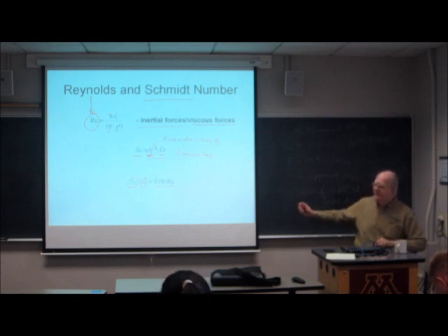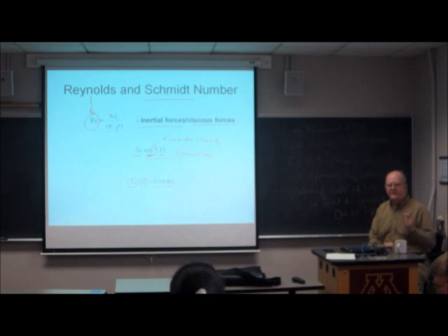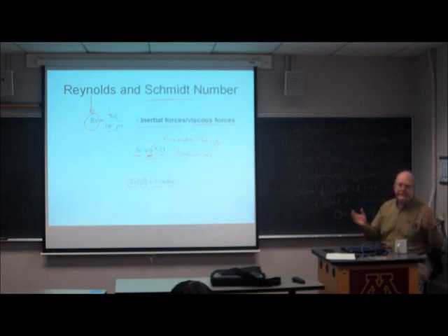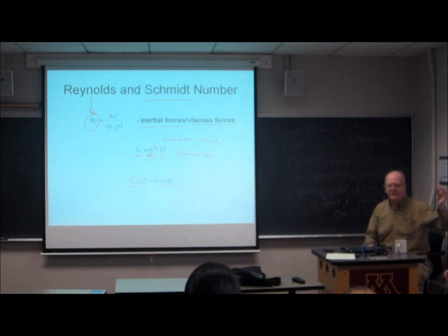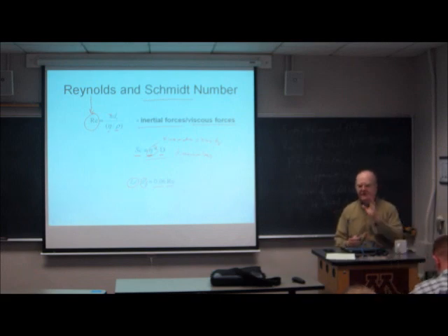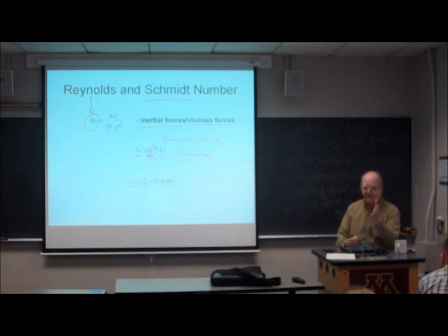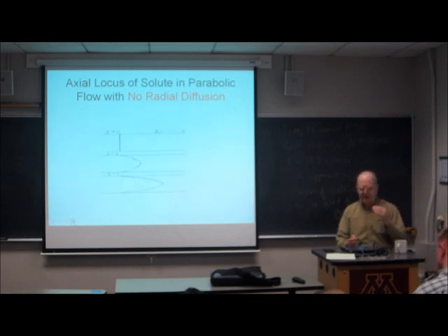Well, if we're talking about a tube that's 30 centimeters long and 0.01 inches in diameter, I mean, 99.999% of the tube is in fully developed laminar flow, and only 0.01% is not in laminar flow. Who cares? Right? So you immediately can assume that the Hagen-Poiseuille equation is correct. So I'm trying to defend the solution to this problem right now so that it's not coming out of thin air. So now, let's go back and think about what goes on in fully developed laminar flow.